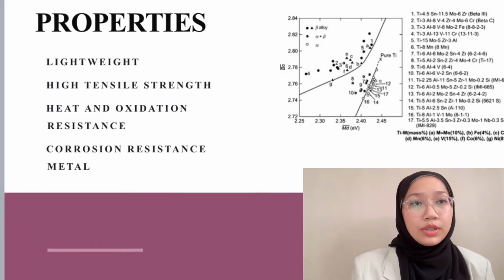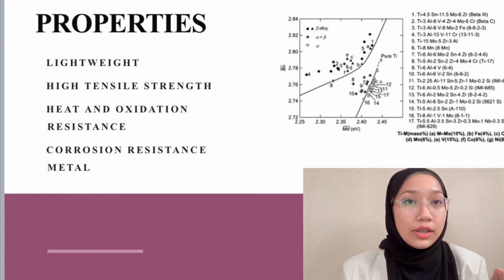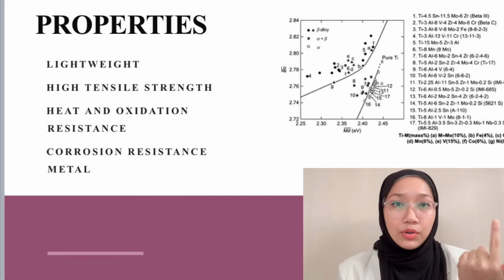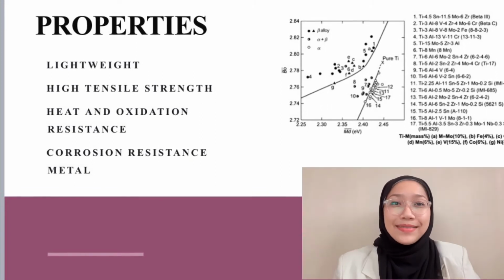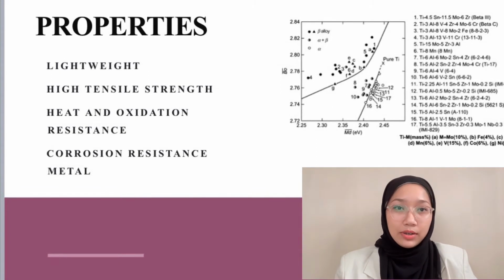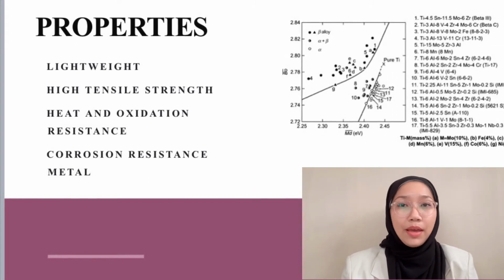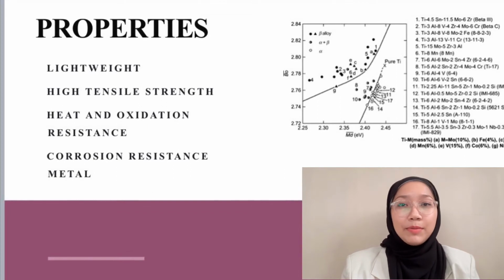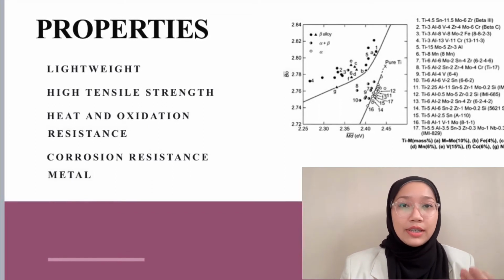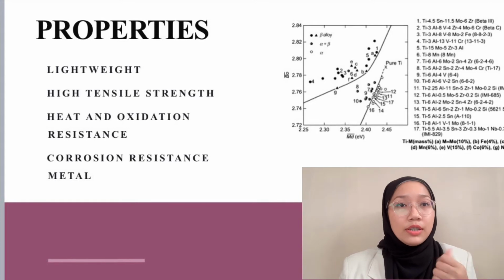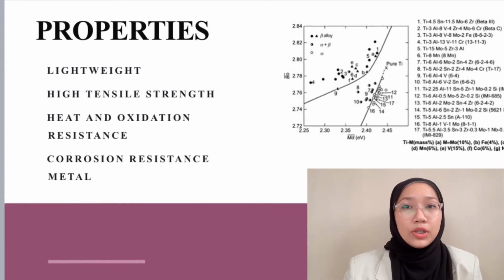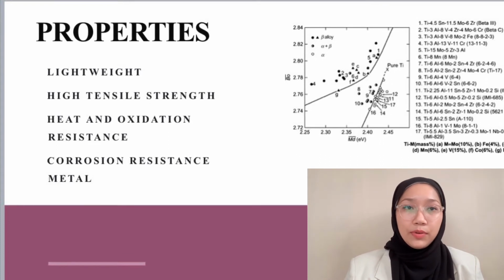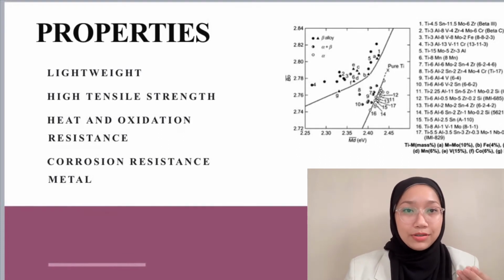Titanium is a corrosion-resistant metal that should be considered for marine and offshore applications where weight, space, corrosion, or erosion are concerns. Since titanium has no corrosion allowance, equipment can be built to meet the bare minimum of mechanical strength and handling specifications. Titanium's outstanding corrosion resistance is due to the metal's stable, tenacious, and permanent oxide film, which is present even in highly contaminated seawater, offshore produced fluids, and all but a few non-produced fluids.